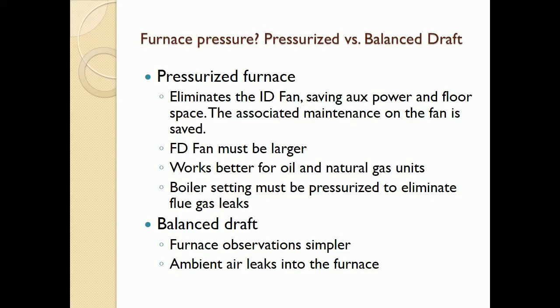The forced draft fan must be larger, and this approach works better for oil and natural gas units. The boiler setting must be pressurized, and as such there is a need to eliminate flue gas leaks. Balanced draft makes furnace observations simpler, however ambient air leaks into the furnace.